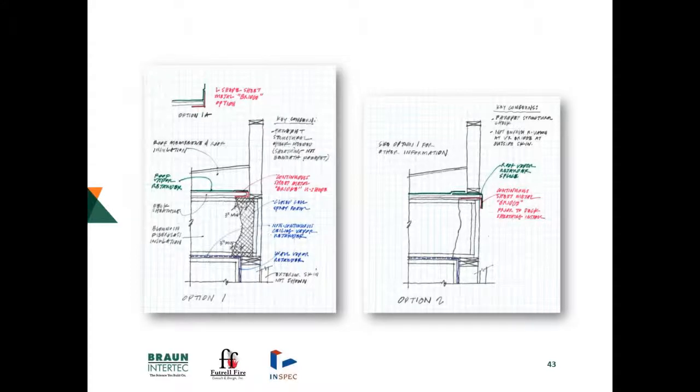These then are our slides of those options we looked at schematically, trying to figure out how to best tie that into the wall roof vapor retarder. First one, we ended up cutting the plywood deck in concept, and their structural engineers didn't like that. Again, this sort of takes care of that structural tendon problem with the parapet.